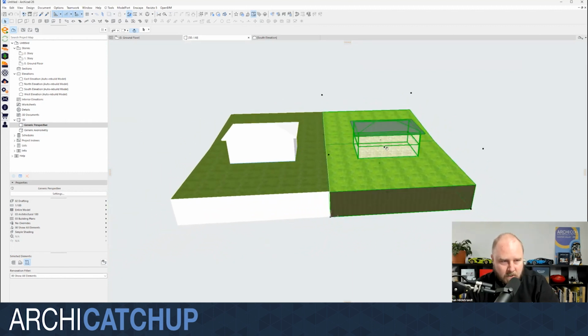And obviously in this instance, we brought in the site as well, but in other cases, you'd see that there'd be other buildings that are associated on this site, and you wouldn't actually turn the site into part of the model. All you would do is geographically reference and make sure that all your models are in the right spot relevant to 0, on your site. And that's how we place them there.